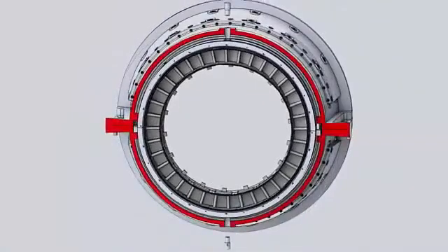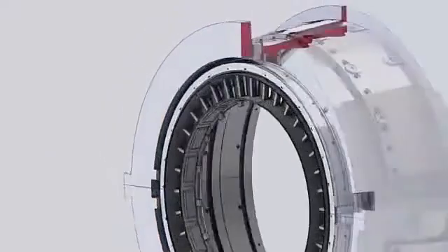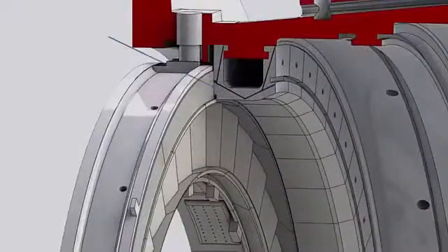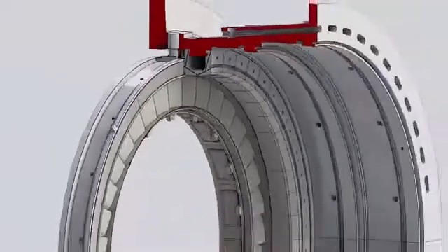The retaining ring is centered by two eccentric pins from the turbine shell. This configuration permits radial expansion due to the high temperatures encountered, while the ring remains centered to the shell. The aft outer face of the retaining ring is loaded against the forward face of the first stage shroud, with seal strips in between to prevent compressor discharge air leakage between the nozzle and the shell.